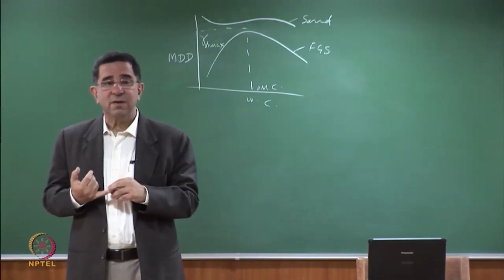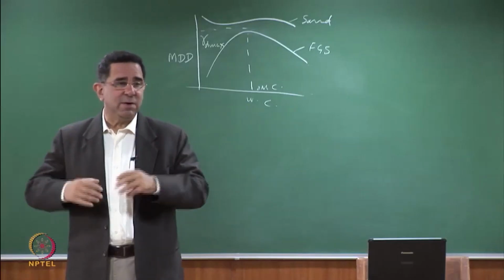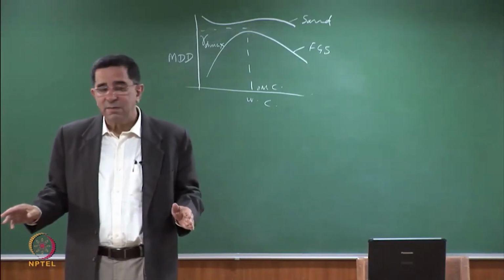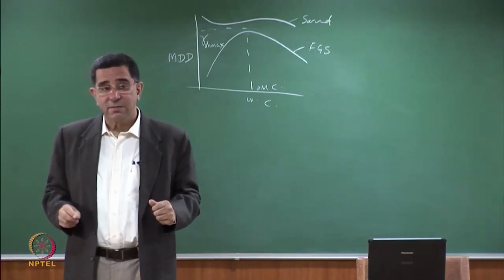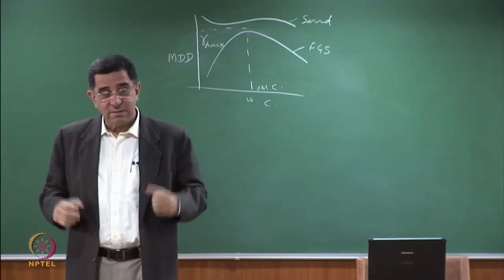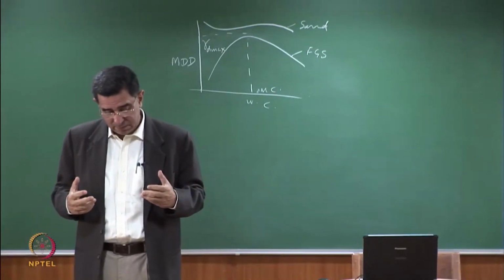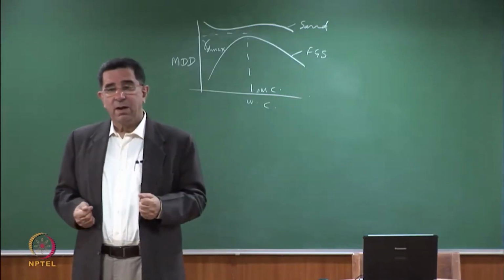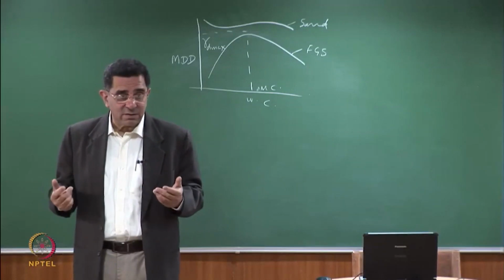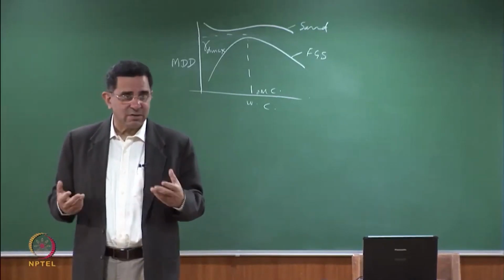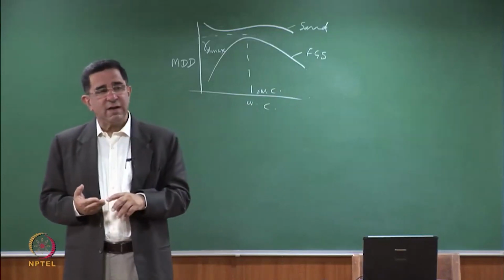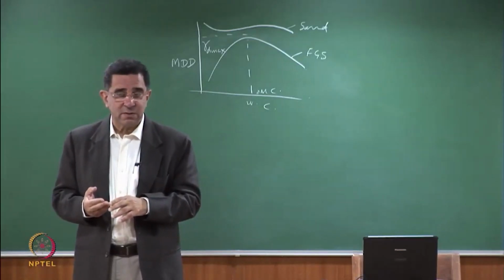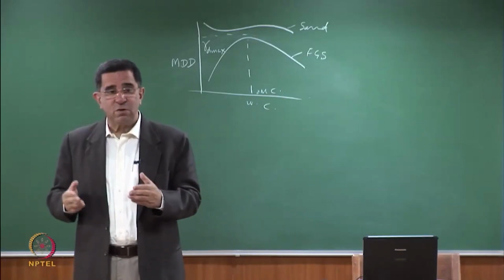Question 1, does it erode more than soil? What does it mean? It shouldn't be that you have made an embankment and when the rain comes, you get erosion gullies and all the ash starts to flow away. Second question, is it hazardous? Does it have any chemicals which may cause bad health? And the third question is, we call it fly ash, is it going to give us a lot of dust? So all these three things have to be addressed when we use ash in earthworks, and when we are going to use geotechnical reuse of material, we will address this.